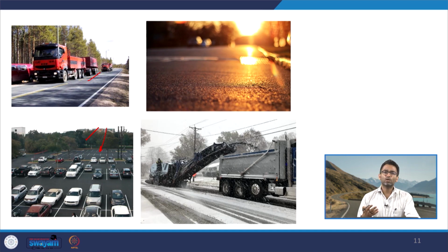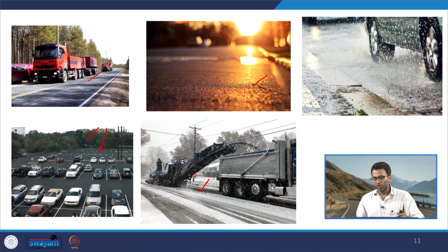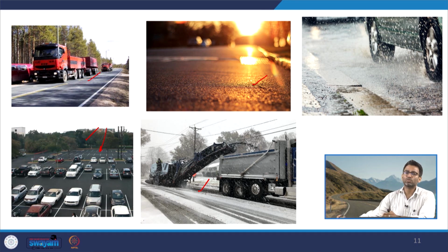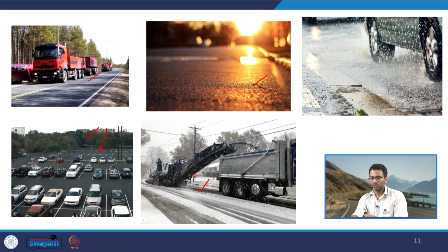While designing the mix for different climates, we have to consider various parameters. For example, the requirement for a mix which will be placed in a very hot weather condition will be different from the mix which will be placed in a cold weather condition. In hot weather condition we will have a tendency to use stiffer binders, whereas in cold weather condition we will have a tendency to use a binder with lower stiffness. Then of course, moisture is one of the factors. At locations with extreme rainfall we have to take several other considerations so that our mix performs when it is finally open to the traffic and to the environment.